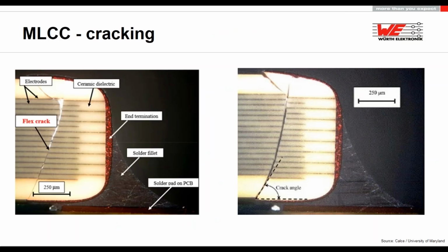Last but not least, cracking is a topic I just wanted to talk with you about. It's a problem you easily can get because ceramic material is brittle. So if you introduce a lot of stress to the PCBs, MLCC can easily crack. This can result in open circuits and short circuits. And what is mainly the driver for cracks?